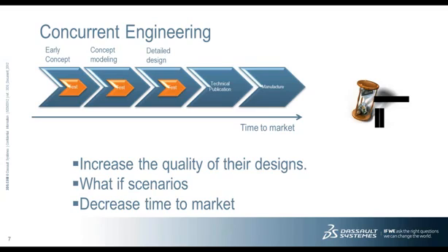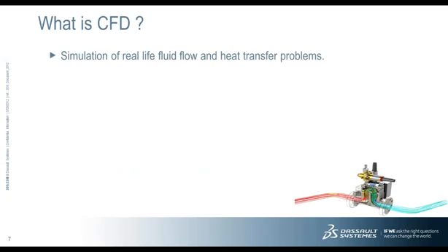The objective is then to conduct fluid flow simulation as a concurrent task during the design process, in the concept or in the detailing design phase, and not only at the end of the cycle, with real prototyping, when usually it is too late or too costly to make major changes in a design. So running CFD simulation during these phases will help you compare design scenarios and find the best one, testing new devices and seeing if they improve product performance while decreasing time to market.